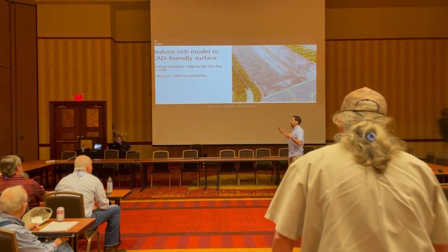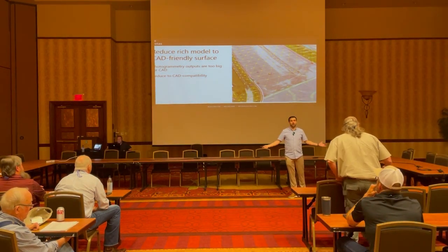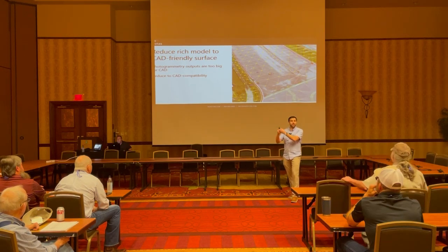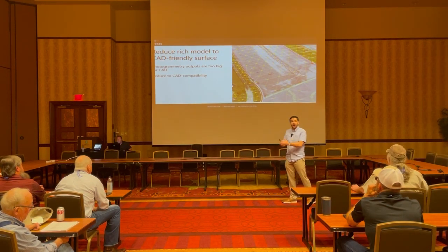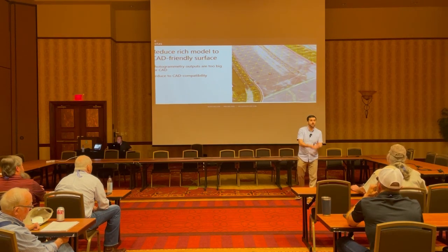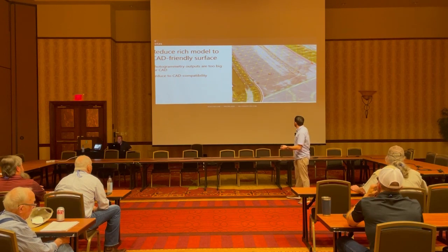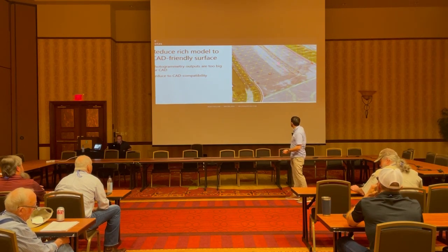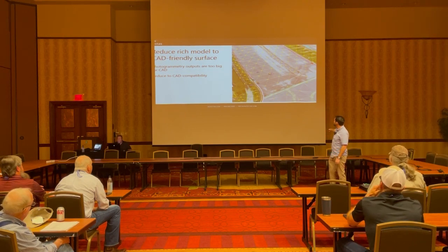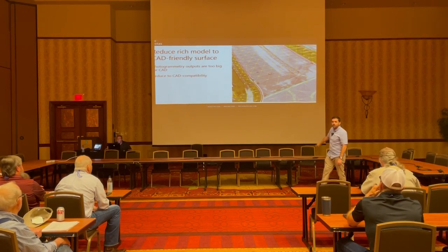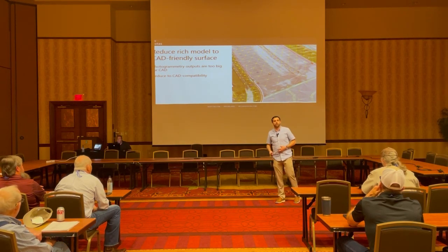So that's why you have to use drafting. This is that stage where you're reducing all of this huge, rich, every leaf on the tree data into something a lot smaller, a lot more easy to use, a lot simpler, and in my opinion, a heck of a lot superior, where you have a clean tin surface like would be demonstrated here, but lines for the curbs, you have your catch basins and drains, manholes, water valves, all of that, all marked, all classified. That is what the line work drafting phase is.